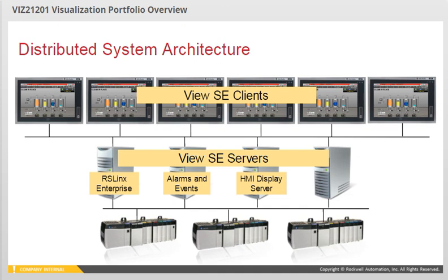By storing and executing these on a server computer, any changes or updates that are made are immediately reflected throughout the system. By comparison, if the individual operator terminals were the repository of the HMI screens, as they would be in a PanelView Plus application, a change made in one place would not be reflected in other parts of the system. In smaller HMI systems, all of these software servers, including the data server, the alarm server, and the HMI display server, might run on one server computer, while in large systems, each one might run on a dedicated server computer.